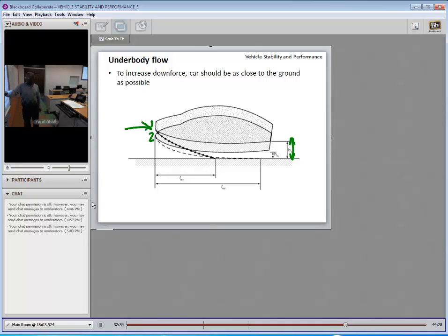The boundary layer is generated, the air flows that way, and it hits the ground at some point there, which is like halfway along the entire length of the vehicle. Whereas if the vehicle is lower to the ground and made aerodynamic, you have your boundary layer built this way, and it comes again. It's more smooth rather than hit the ground here, which will cause lift.